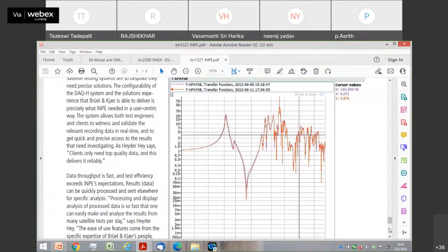Because data doesn't vanish. It could happen that the sensor went into saturation or something. But the ideal thing is to have 2 or 3 sensors close enough and look at all their data and see whether it is a problem with the sensor, the cable, or the DAS.